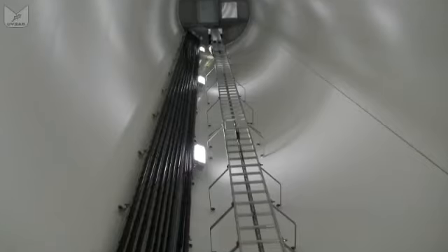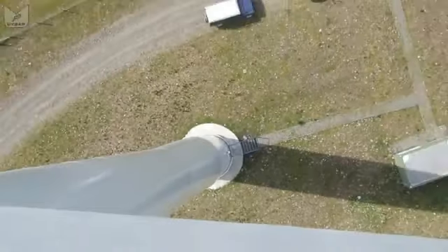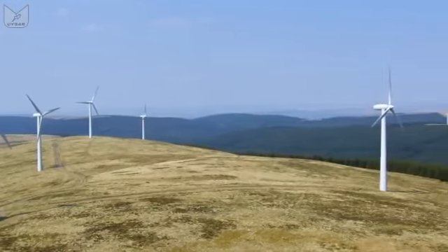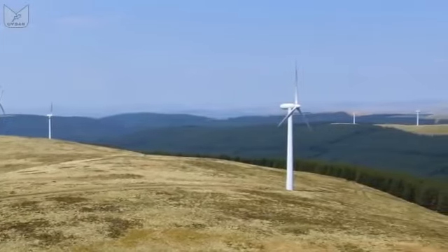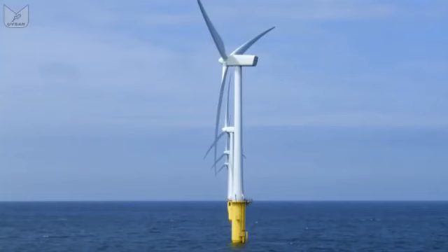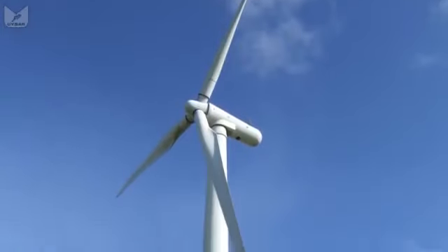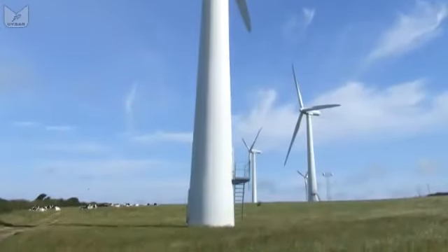We tend to class turbines by their power output, and hence their physical size. Wind farms might use many sub-megawatt turbines, each producing 400, 600 kilowatts each, or a few multi-megawatt turbines, producing maybe up to 3 megawatts per unit. Apart from physical scale, they are arranged a bit differently, so let's start by looking at a typical sub-megawatt model.